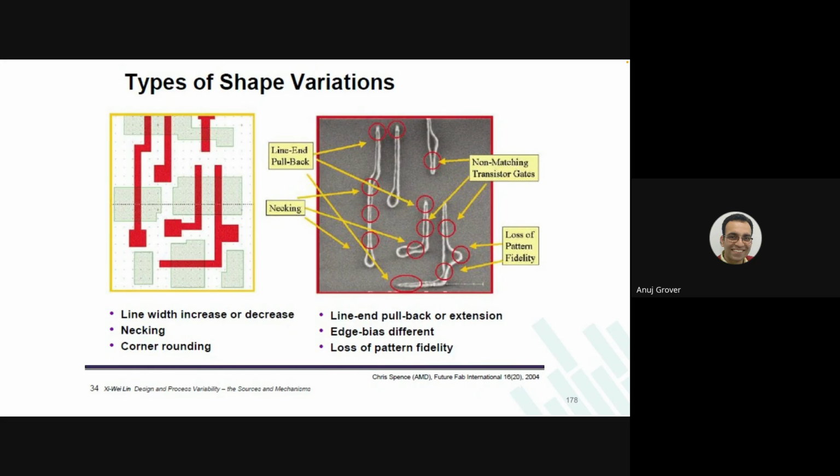It is about when you have multiple lines running, the end line, because it's on the edge of the structure, will have a different bias, a different kind of, let us say, bending or shrinking, than the remaining. So to avoid this, again, this is a structural thing, DRC is changed.